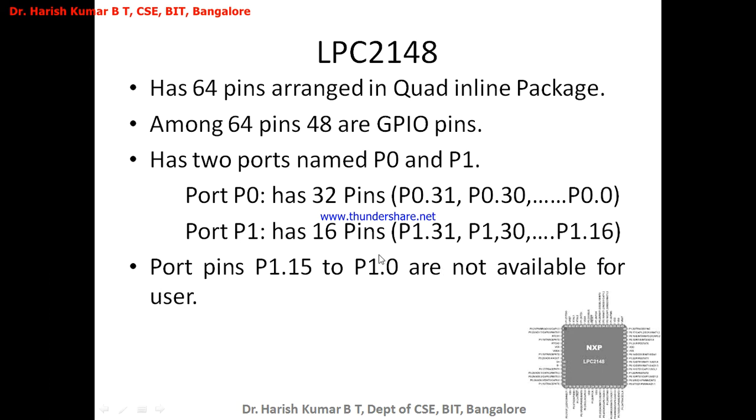In port 1, the port pins 1.0 to 1.15 are not available to the user, so they are used by the LPC2148 itself. You cannot use these port pins from port 1 for programming purposes. What you can use is P1.16 to P1.31, whereas in port 0 you can use all the pins from P0.0 to P0.31. This has 32 pins and this has 16 usable pins, and together that is 48 general purpose input output pins.